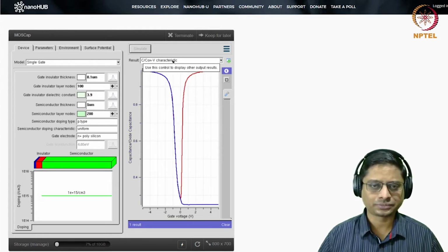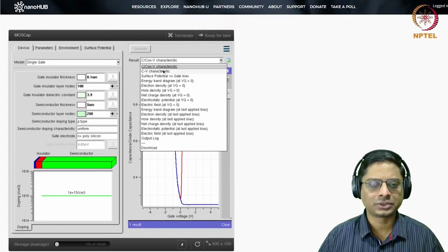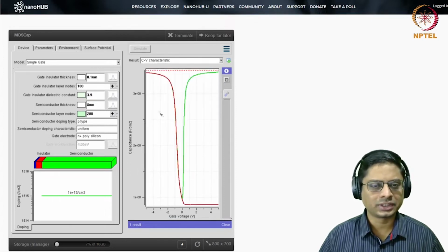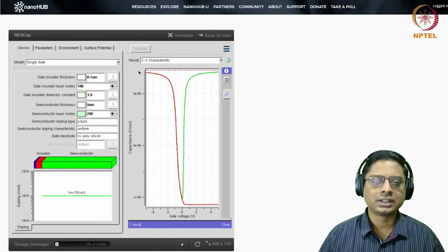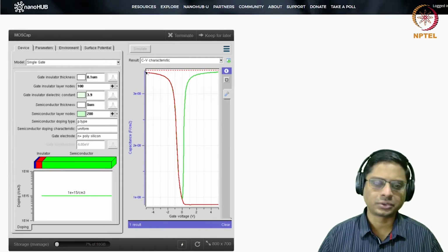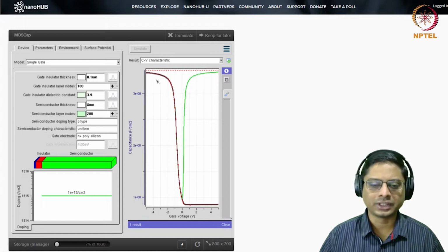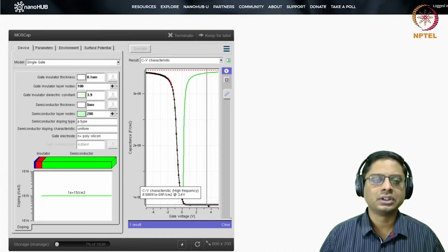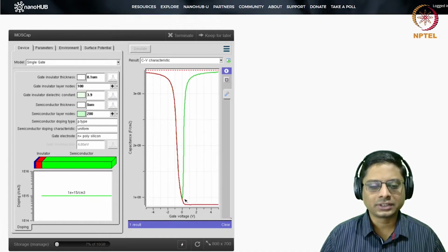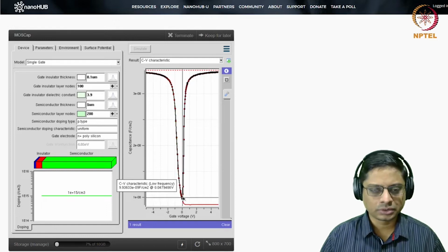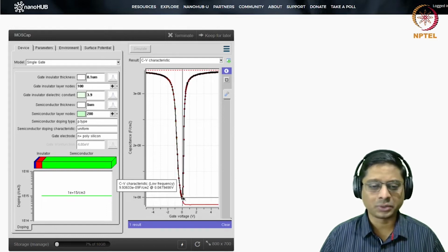If you want to look at the standalone capacitance, you can also see that. So you see that it is about, I would say, 30 nanofarad, 35 nanofarads also, right? So this is 34 nanofarads at this point. Okay. And then you see that in the inversion you have the flat, high frequency CV characteristic. Okay, and notice that the threshold voltage is close to 0.05, 50 millivolts, right?